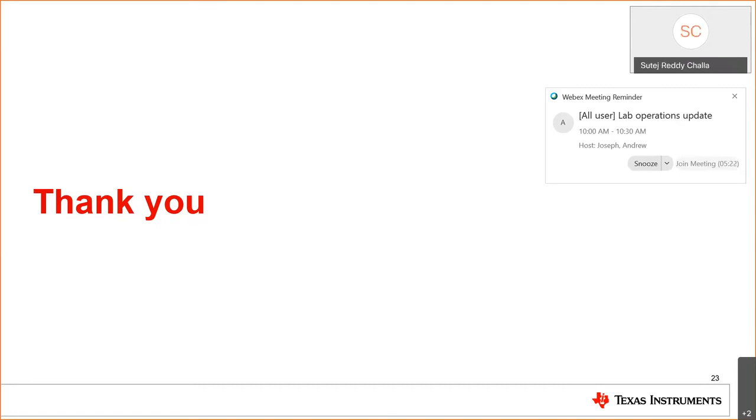Yeah. So the negative gate drive, although it is not absolutely required in the flyback topology, as I said, from the perspective of the shoot-through, because there is no chance for a shoot-through because of only one silicon carbide FET, right? However, having a negative gate drive is helpful to improve the efficiency of the flyback converter, because having a negative gate drive will help the SiC MOSFET to turn off faster because you have more negative bias, right? And also, typically these SiC MOSFETs have a high internal gate resistance, which would slow down the turn-off in case there is no negative gate drive.